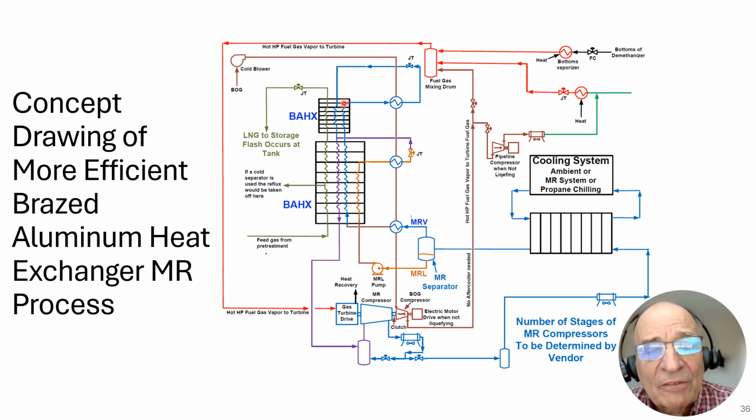Now we have MRV which happens to no longer be a vapor, but it now is a liquid, containing a high percentage of methane and nitrogen. It goes through a JT valve and flashes at a very cold temperature. It flashes at minus 280, and it goes down. It gives up its refrigeration by absorbing heat from the LNG, and absorbing heat from the MRV, then continues down.